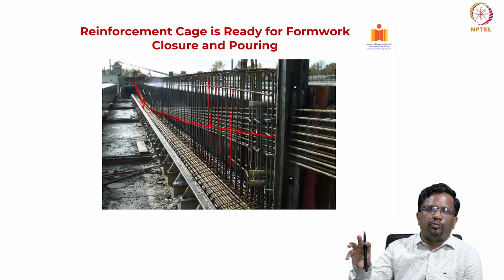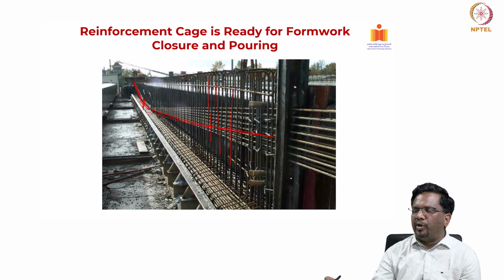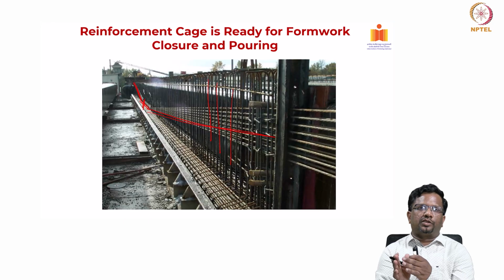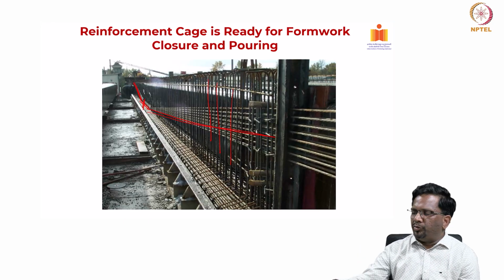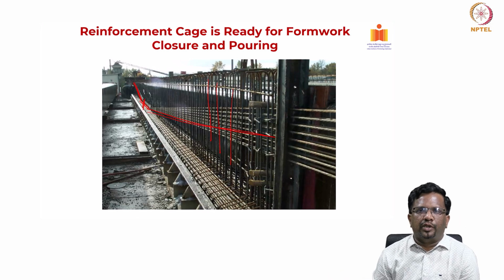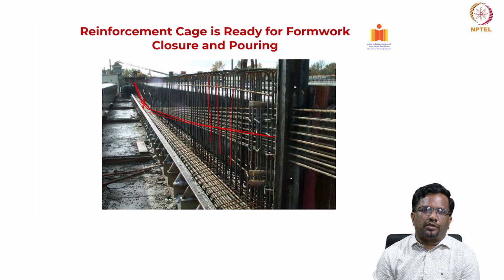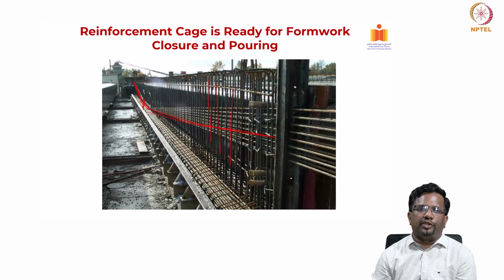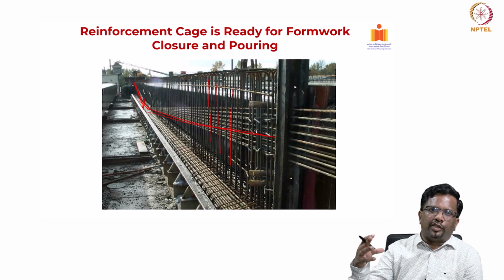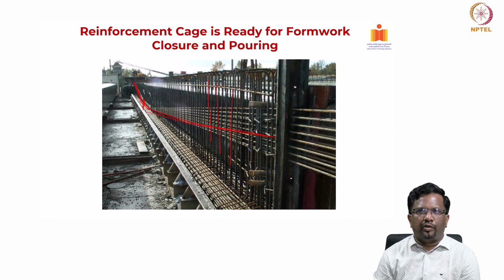Then only will it develop more pre-stressing moment that will help offset the loading coming from external load. Then as we come towards this anchorage zone or the bulkhead location, the strands will get splayed. The reason is we want to reduce the stresses at the bulkhead locations so that you are not going to have any failure when you cut the strand. So typically these strands get splayed as you move towards the support locations, so that while you transfer the pre-stress and do the stretching, you don't have any problem of premature failure.